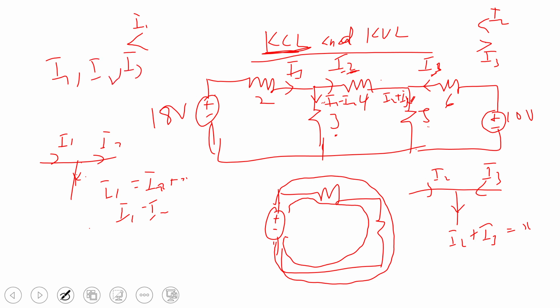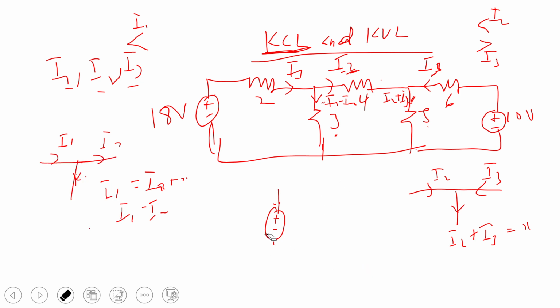Now, in using Kirchhoff laws, every time the number of currents that you have assigned within the circuit would determine how many loops you need to take. So now I have I1, I2, I3. It means that in this circuit, I need 3 loops, and I'll be able to solve this question. So now I'm going to take 3 loops within this problem.